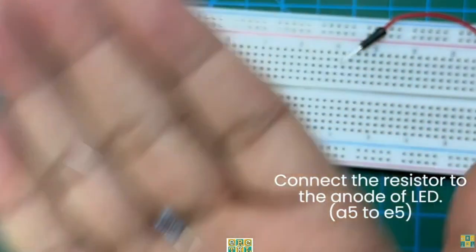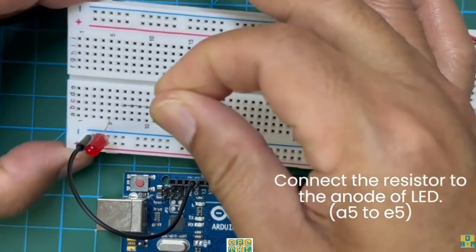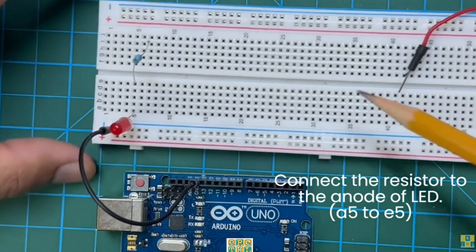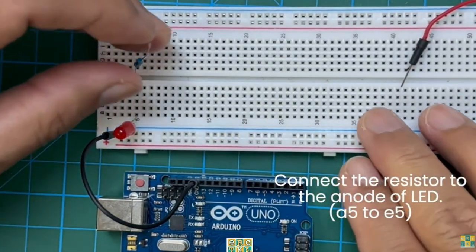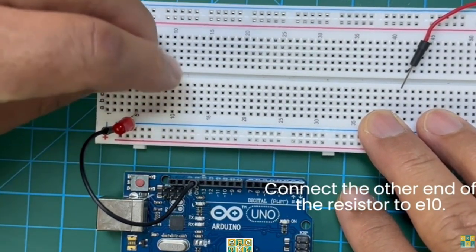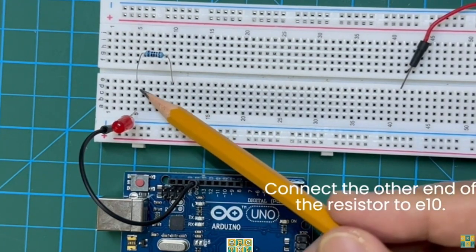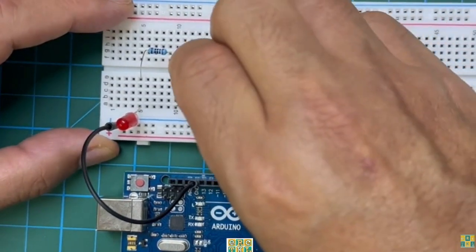We need to put a resistor in series with our LED. So the 1 kilo ohm resistor will be connected to either B, C, D, E, but I chose letter E. That will be in series with letter A. So E5, I connected A5 to E5. And then the E5, I connect to vertically number 10, but on letter E. So I connected the resistor, the other end on E10. Therefore, whatever I connect to A, B, C, D, 10 will also be connected to the resistor.